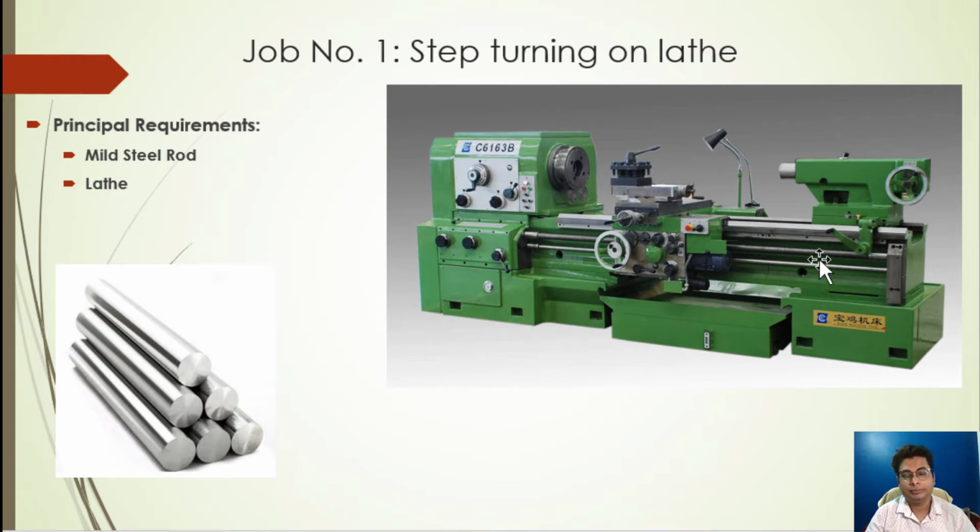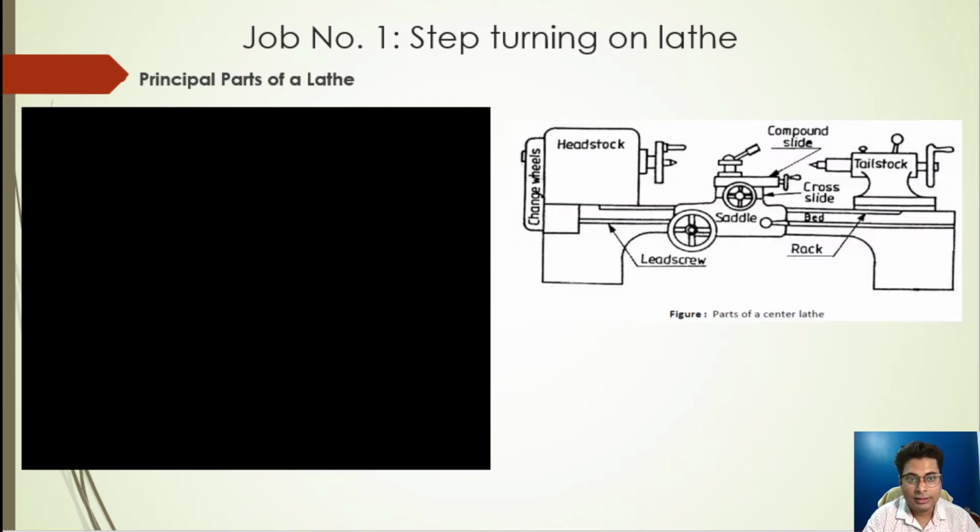Okay, now different speed and feed can be controlled on this lathe. The rotating speed of this chuck when the workpiece is mounted, and the traveling speed of this carriage, which holds the tool post and the tool, can be adjusted by changing the levers over here. Okay, so let us see a video in order to understand this a little better.